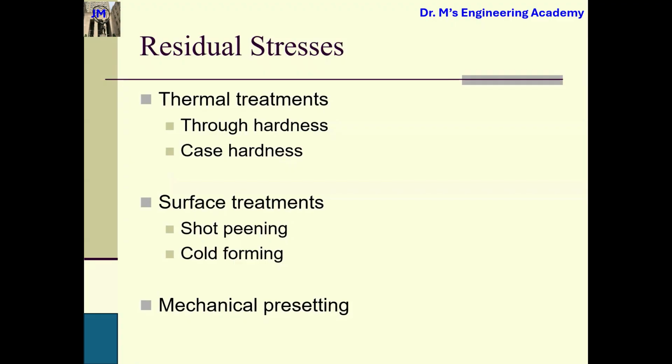I want you guys to write down. First, improve the hardness of the surface. Second, induce a beneficial compressive residual stress, and enhance the fatigue life of the component. Two things: hardness itself, and second, we induce the beneficial compressive residual stress. This is the first category.